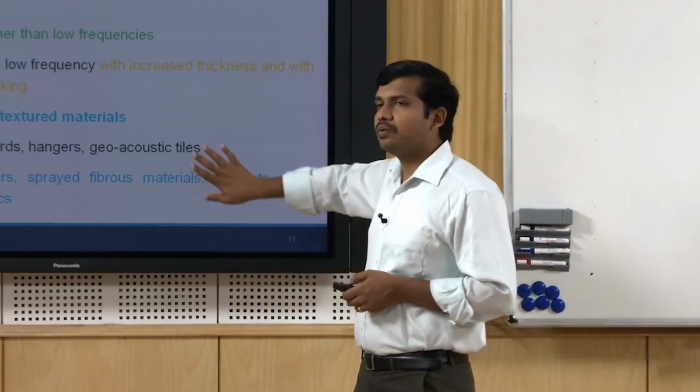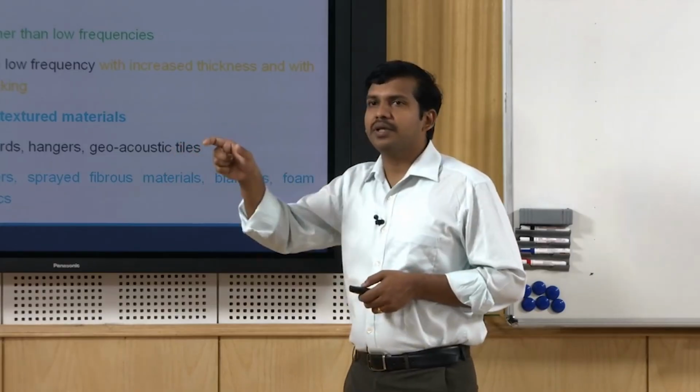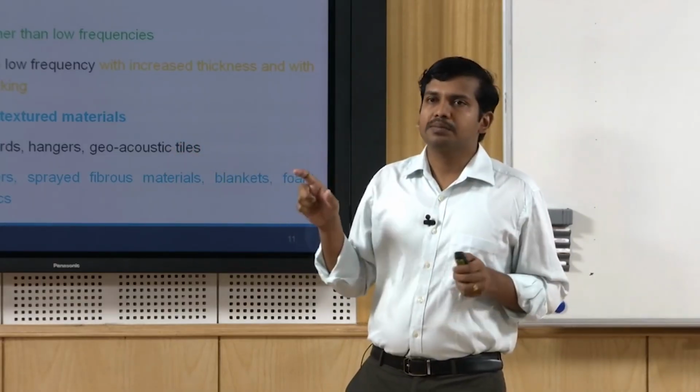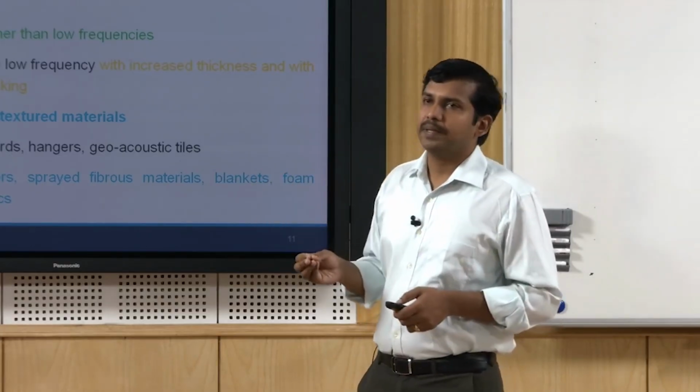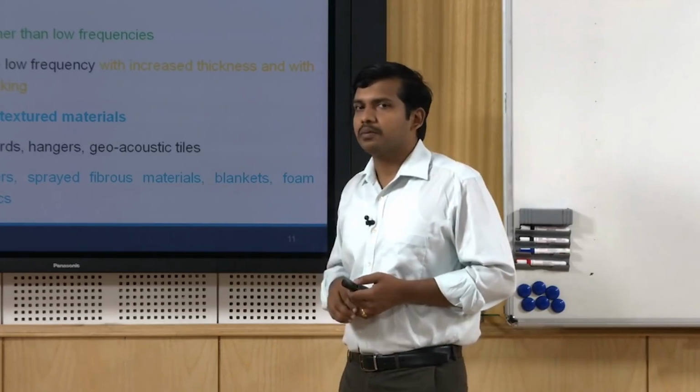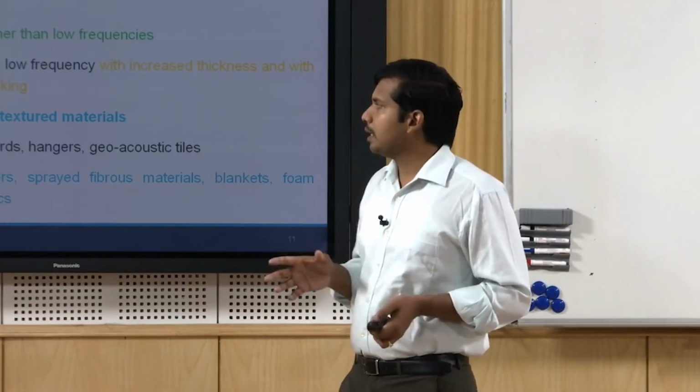But if you are simply mounting it on the wall surface, a thin 50 mm cushion, standard panels, boards are available. If you are simply going to mount it, then you can only expect a very good performance in the high frequency. Low frequency you cannot expect much.